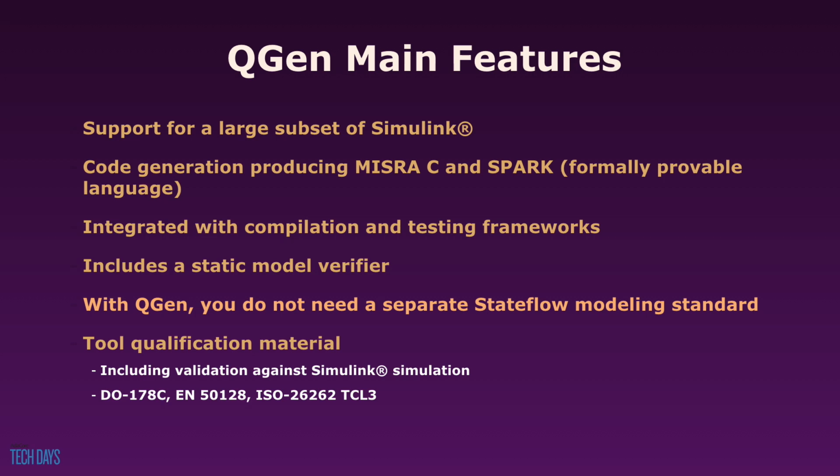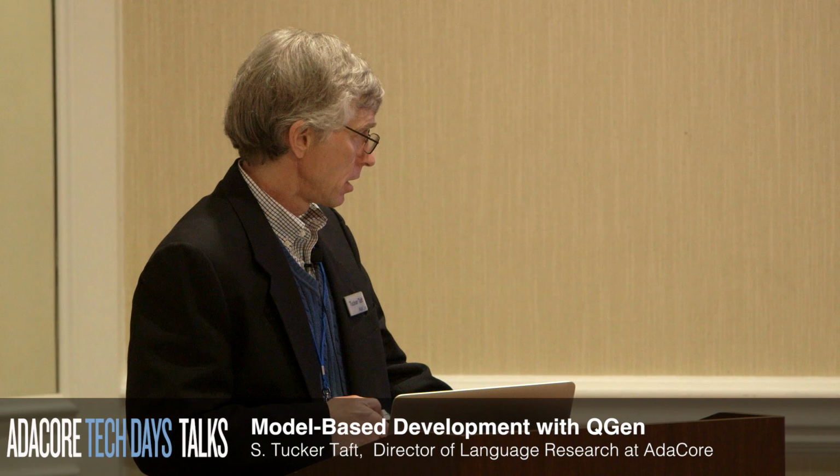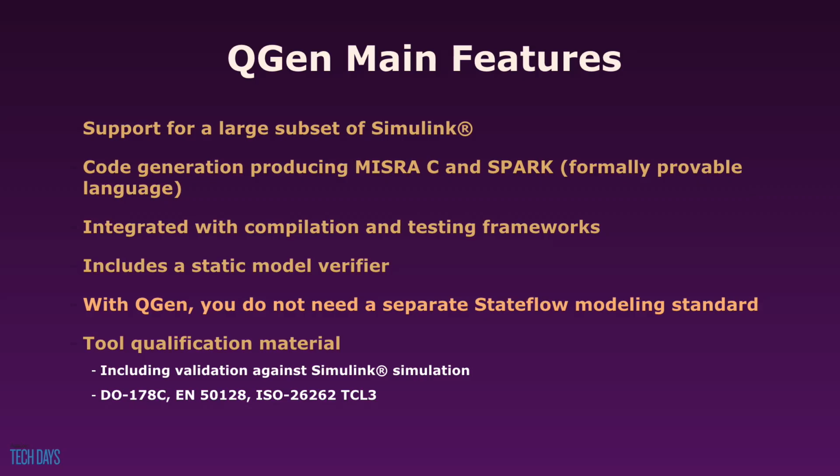Finally, a very important aspect of what we're doing is that we are intending to build a qualified code generator, and what that means is that we will go through sufficient testing to verify that every model block that we support is turned into the appropriate C or Ada code that has a thorough test to ensure that it's an exact equivalent, no added code, no less functionality than the original model block. In the DO-178C terminology, this will be TQL1, which is the highest level of qualification for a tool.